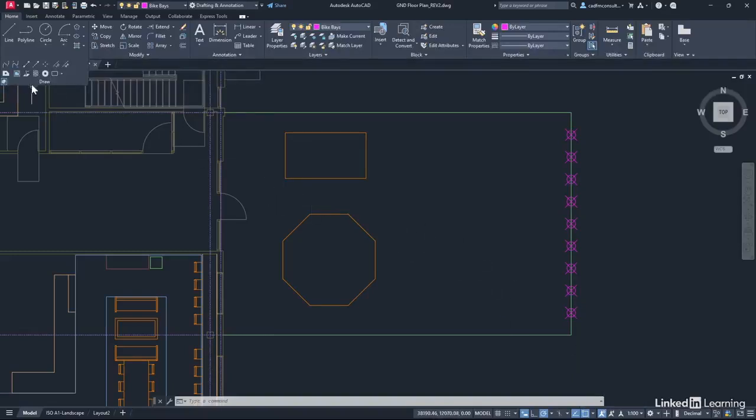We're going to go up to the draw panel, click on line there, like so. And then if we hover over that, can you see we get a node snap? And look at the symbol. For node, it's the same as our point style. Just kind of makes it easier to see, if you get what I mean. Click on node. You're going to come out horizontally like that. Can you see? Polar tracking kicks in. And we're going to make each of these bike bays 4 meters long. So we're going to type in 4,000 millimeters. Press enter. And there's our bike bay there, like so.